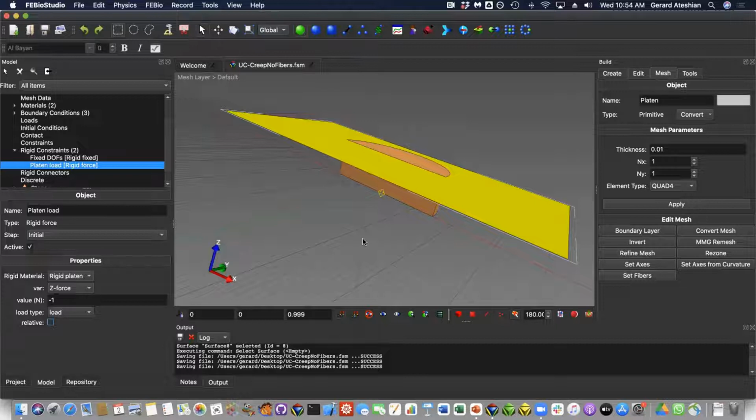Normally you would say, well, a creep problem should be a step load. The answer is yes, but it turns out that 1 Newton load is going to cause finite deformation. So really we should ramp it up relatively quickly. So 1 second over the time duration of our analysis. So I have now all the boundary conditions.